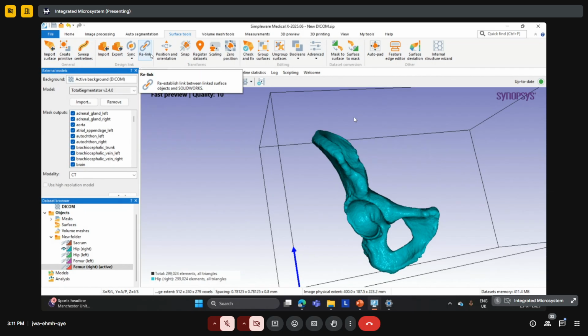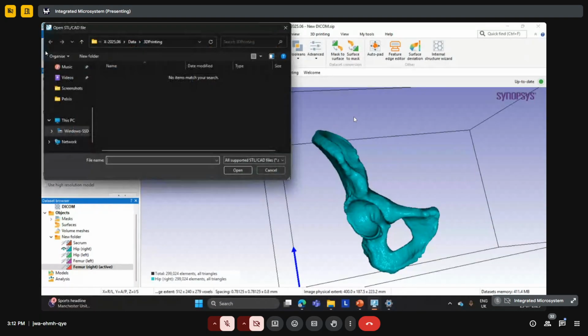For example, one might ask, if we don't have SolidWorks and we are using another tool such as Freeform or any CAD designing software like Blender to develop an STL file or CAD file, how can we import the surface in that case? So that too is covered. We have the import surface option in which we have the STL, stereolithography file, PLY file, IGS file, STEP file.